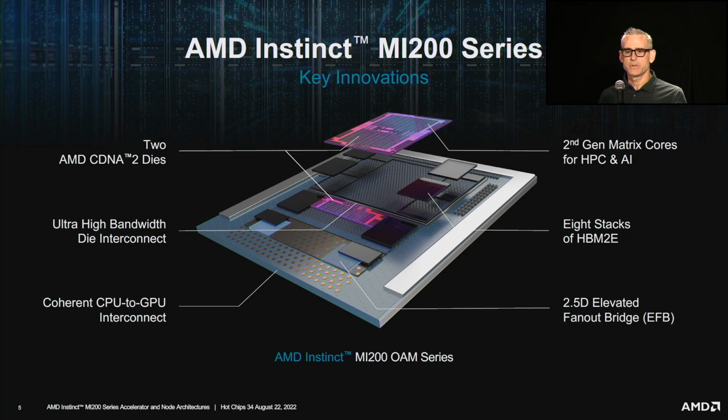Elevated fan-out bridge provides the density required for terabytes of bandwidth between the HBM stacks and the compute dies, while high-speed Infinity Fabric is connected through the package substrate. This solution has proven robust and manufacturable, allowing AMD to deploy MI250X reliably at exascale.